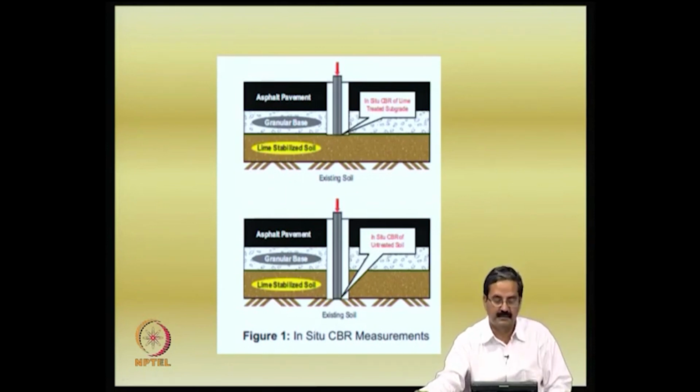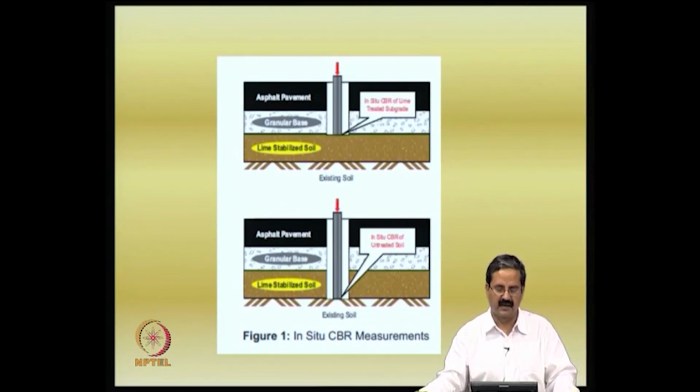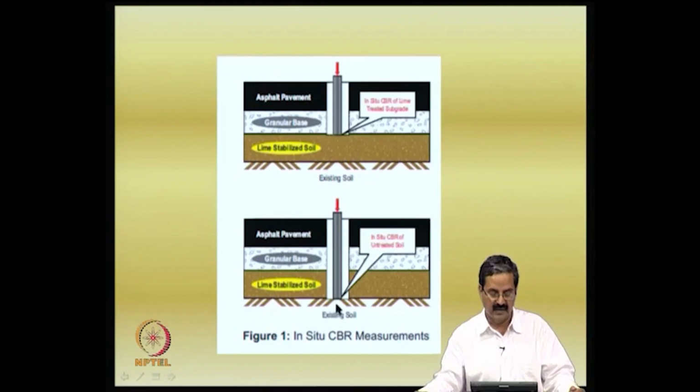I will just give you some example of durability studies that were conducted by a company which deals exclusively with lime treatment. In fact, they have taken lime treatment as their own profession, and then they go about doing this job very well. Similar to field CBR, similar to in situ laboratory CBR, we can also do the in situ CBR test. They have done the in situ CBR test for the existing soil and then lime untreated soil. So this is what, say for example, the in situ CBR of the lime treated soil was done at this point, in situ CBR of the untreated soil was done at this point.